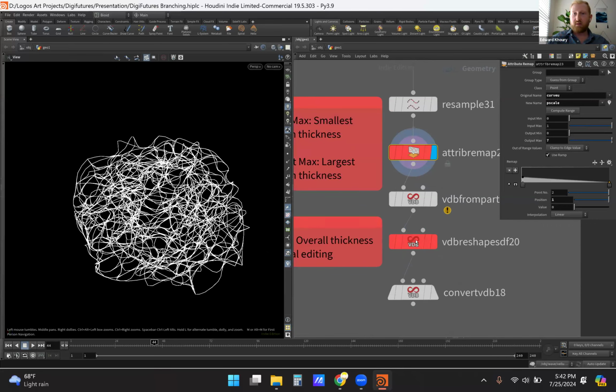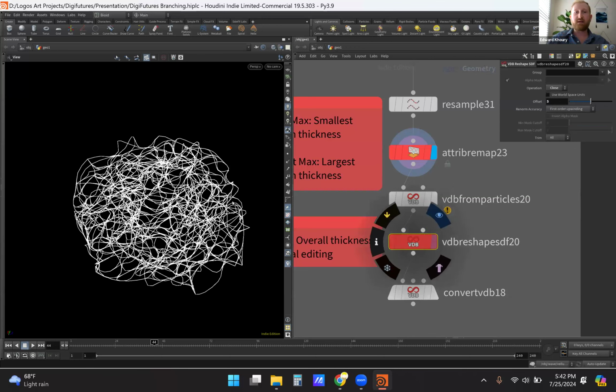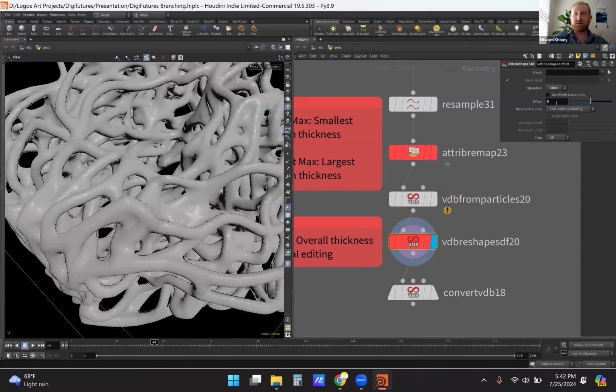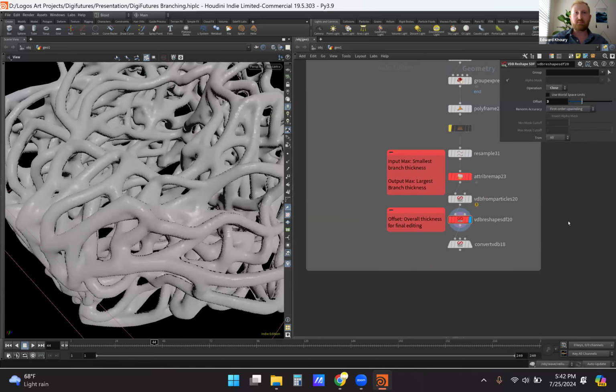And then you can also do some final reshaping through the offset. What that does is, in between the gaps of the connections, it'll offset along here. So let's say if I make it 3, it makes it more linear connections instead of being kind of rounded out like when we had it with 5.